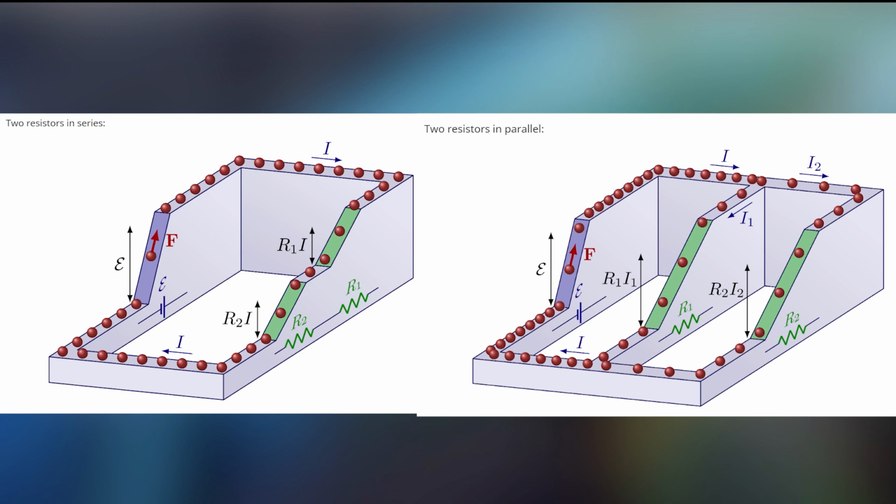And the reason you'd want to do that is because you want to prevent a short circuit or some sort of electric accident. If too much current is flowing through the wire, that means there's some sort of short circuit, and you're at risk of fire. Therefore, the fuse will blow, it will break the circuit, and current will stop flowing. So this is an example of a negative feedback device. If you get too much current, it causes less current to flow. Circuit breakers are better than fuses because you don't have to replace them. You just flip the switch and it's working again. But they fulfill the same purpose.